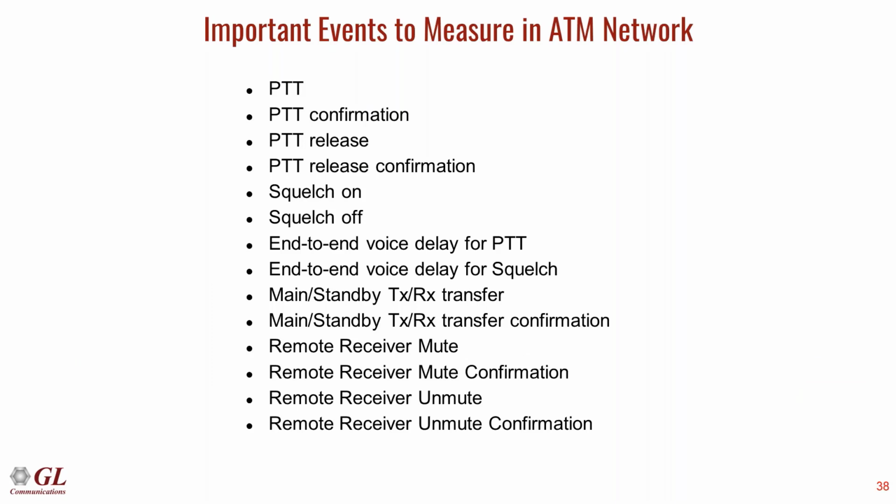Just to tell you, for example, PTT, confirmation, release, squelch: these are all end-to-end voice delay. There are a lot of other important real-time signals that have to be transmitted in critical time, like, for example, main/standby. If there was a failure and you wanted to transmit over the standby, all of these things have very critical time requirements. This is just a sampling of some of the timing events that are there.